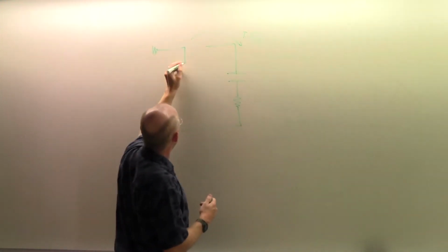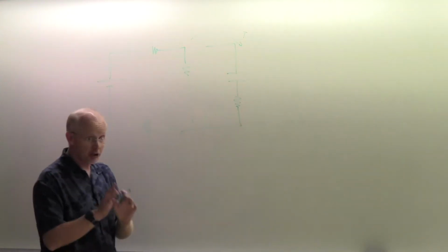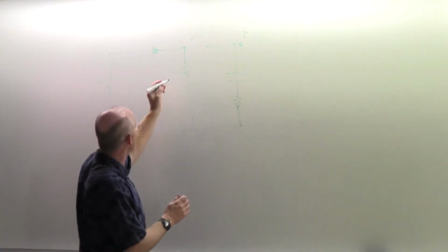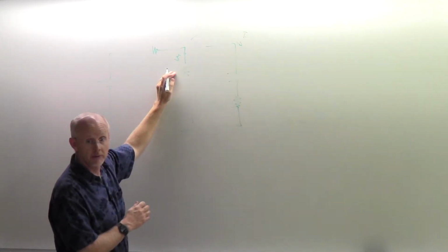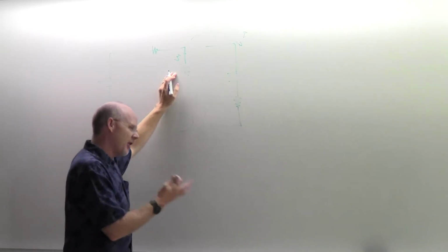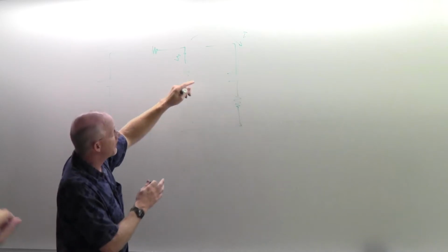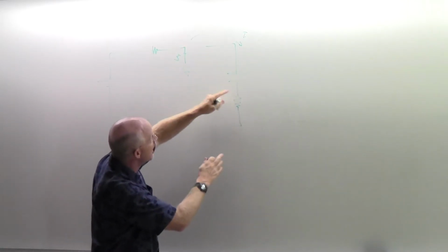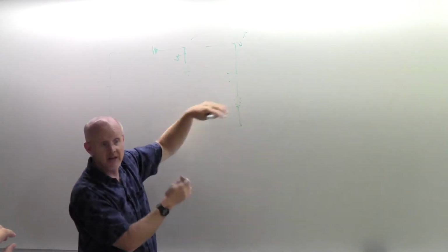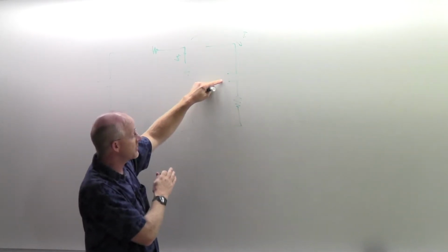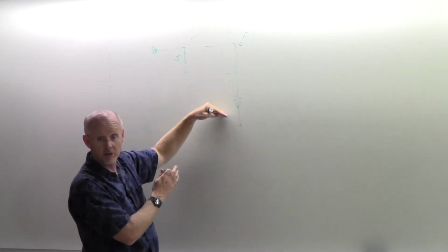As we already said, this is going to divide the 9 volts. I'm not sure how much, but for the sake of your question, let me say this is 5 volts, which is terrible to say because the current is going to vary here, and so it's not always 5 volts. But what I'm trying to say is at first, there's no charge on here, so all 5 volts is here. Then as time goes along, this might have 1 volt, so this has 4. This has 2, this has 3. Eventually this builds up to 5, and that goes down to 0.